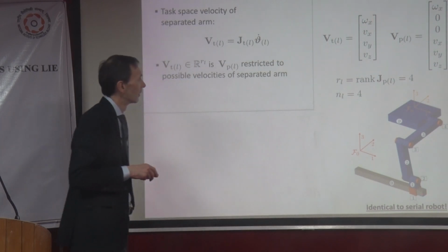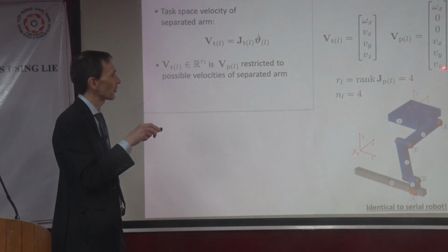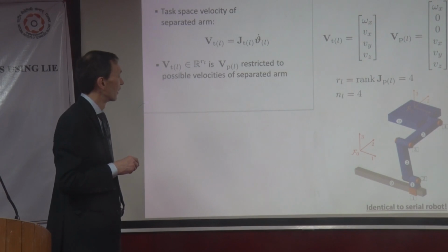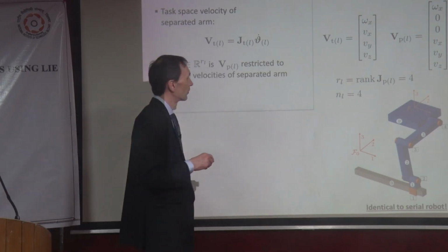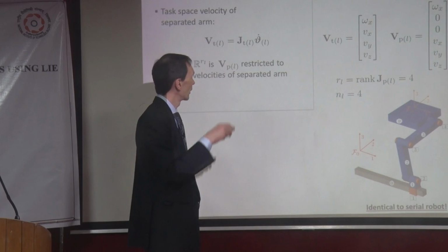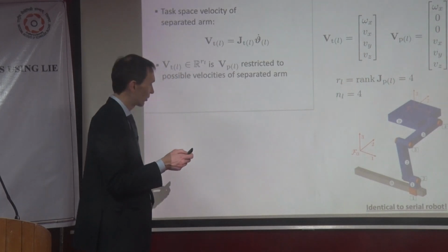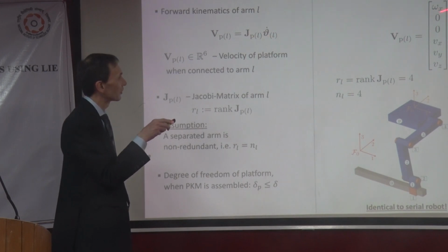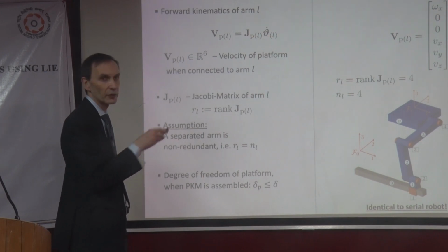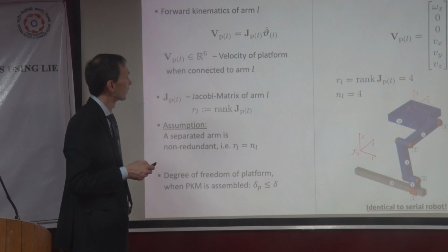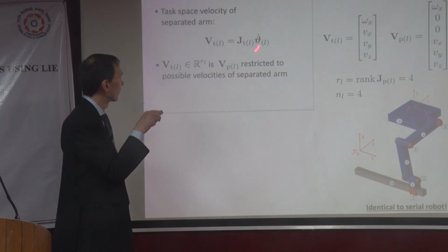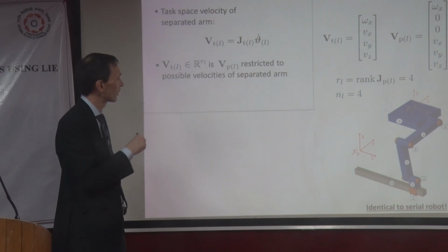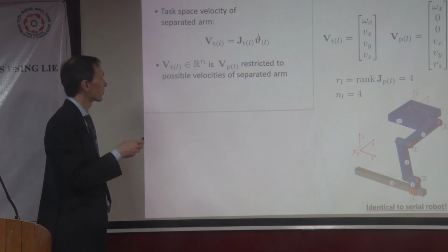And we get this from the twist by just eliminating the zeros. And correspondingly, when I eliminate these zeros, then of course in the equation that we had before, I have to eliminate the second and third column. And the corresponding Jacobian that we get when we delete them, we call it JT.